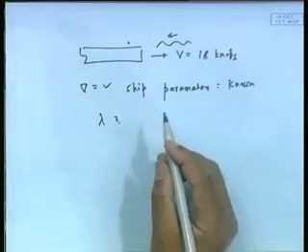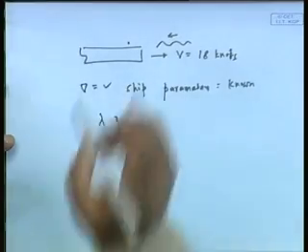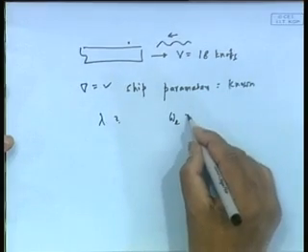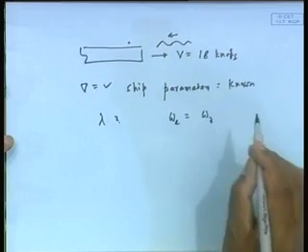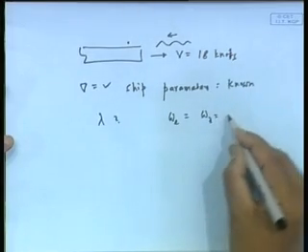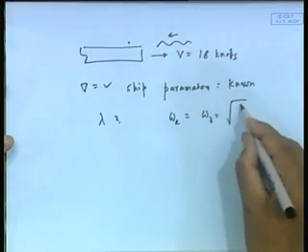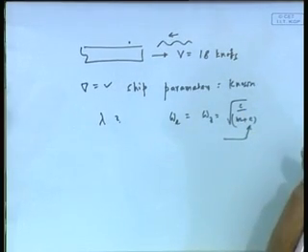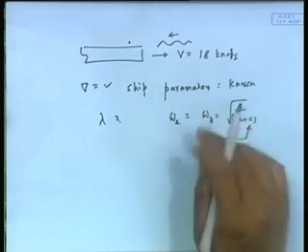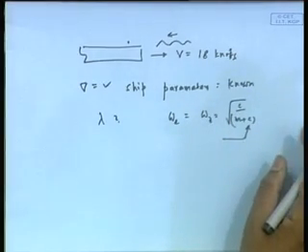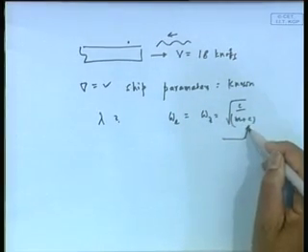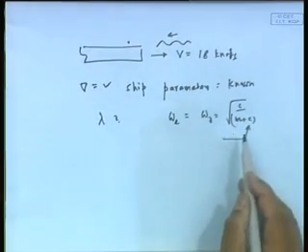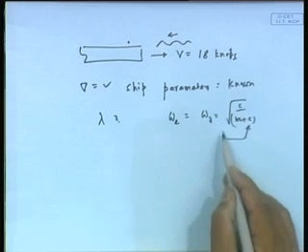The problem is very simple, because excessive motion obviously means the wave exciting frequency omega is equal to the natural frequency omega z. This is equal to, of course, root over of c by m plus a. Of course, I have to make some estimate of a. Without that, you cannot proceed. So, how do I go? I can estimate a. I of course know c and m from hydrostatics and mass inertia. So, what will happen from there?